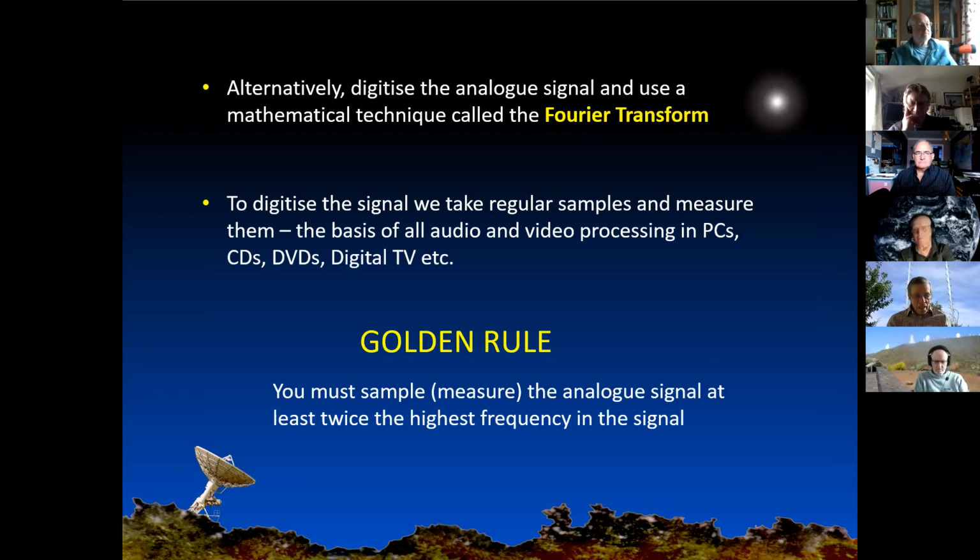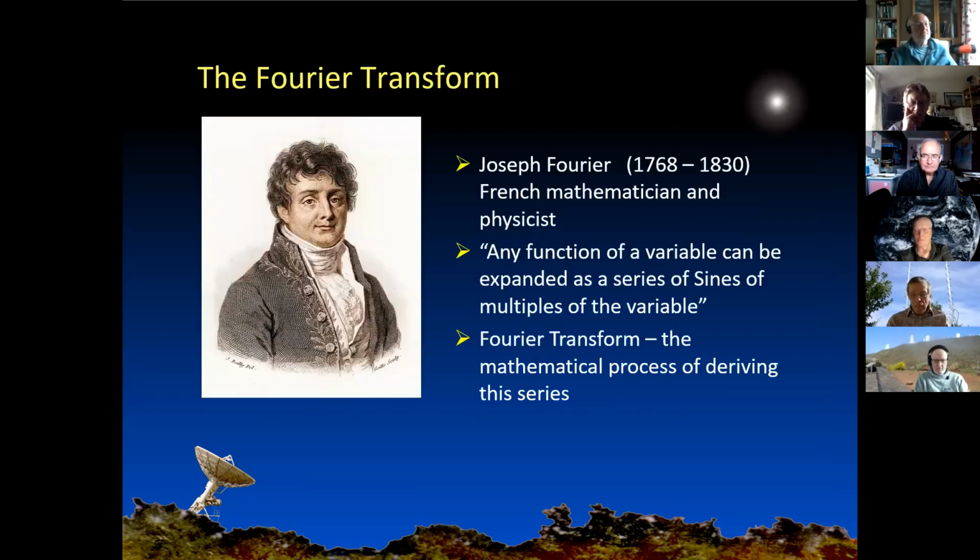The golden rule, which you'll get absolutely fed up of me mentioning as we go through, is that if this is going to work, you must sample, measure the analog signal at least twice the highest frequency in the signal. Right, okay. So just a bit of background.